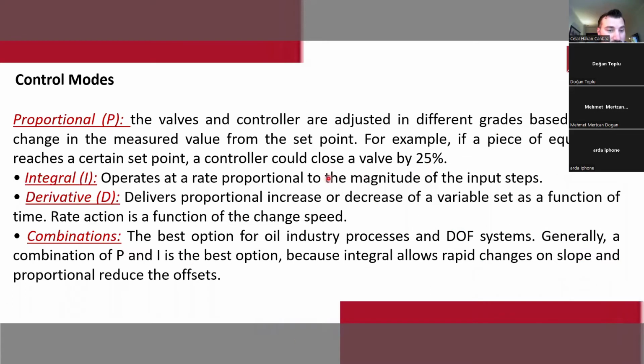The integral one operates at a rate proportional to the magnitude of the input steps. The derivative one delivers a proportional increase or decrease of the variable set as a function of time, and the rate action is a function of the change speed. And yeah, this is the D one.